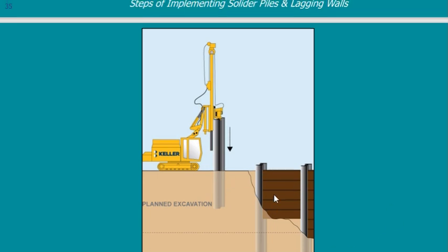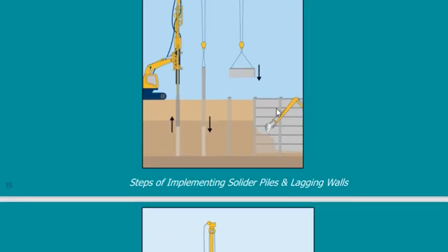So what I'm going to do, I'm going to go to the site and start excavating. I will just excavate a small depth. I can do this with soil that is medium or a little bit. I need soil that if I excavate, say 50 centimeters, it does not fall. So what will happen? When I excavate the first layer here, I put something called wooden lagging.